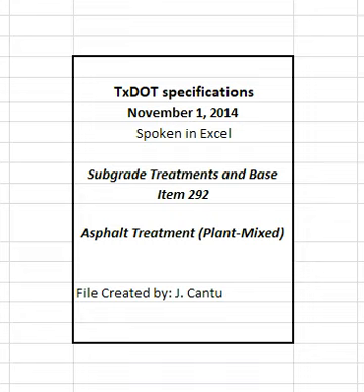Use lightly oiled tamps to thoroughly compact the edges of the pavement along curbs, headers, and similar structures and in locations that will not permit thorough compaction with rollers. The engineer may require rolling with a trench roller on widened areas, in trenches, and in other limited areas. In-place compaction control is required for all mixtures. Complete all rolling for compaction before the mixture temperature drops below 175 degrees Fahrenheit. Unless otherwise shown on the plans, use density control.